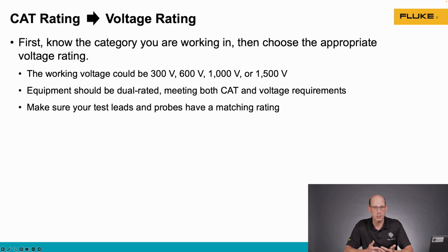Now an issue arises where if those probes should be damaged, it may be tempting to go into the shop and just pull any test probes you have off the shelf, but there's a pretty good chance those probes are not going to have the same rating as the meter because that does have a high voltage and category rating. So make sure if you're replacing your test leads, you're replacing them with a set of test leads that matches the rating of your test instrument.